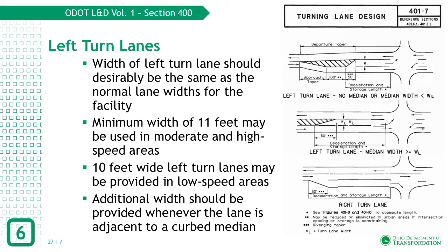The width of the right turn lane should be consistent with the normal width of the facility, but additional width may be warranted on roadways with curbed median sections to account for drainage spread.